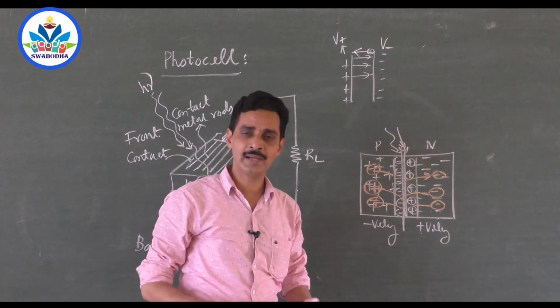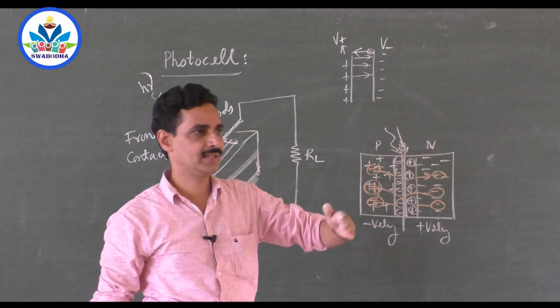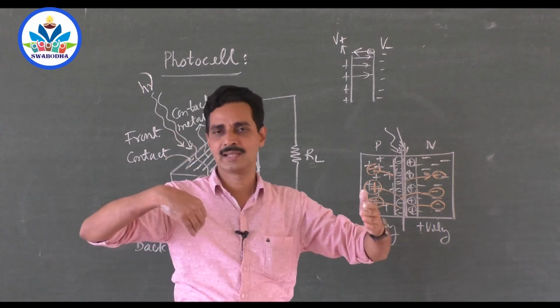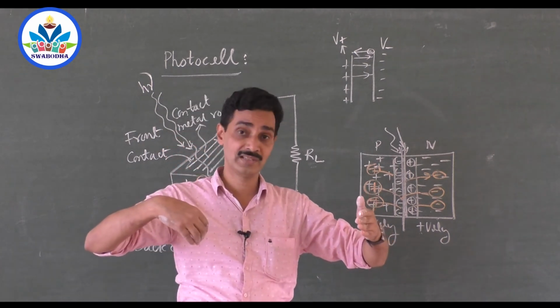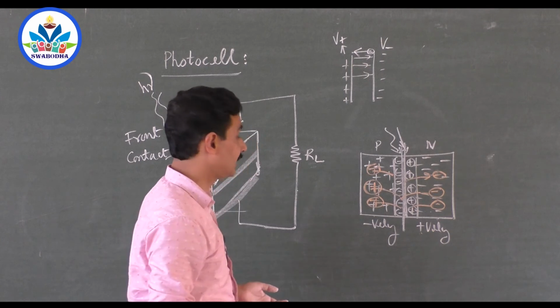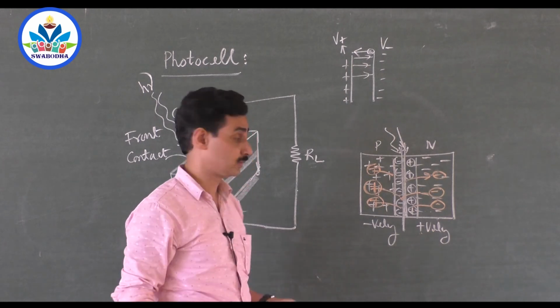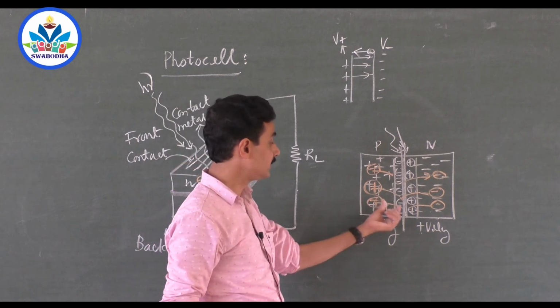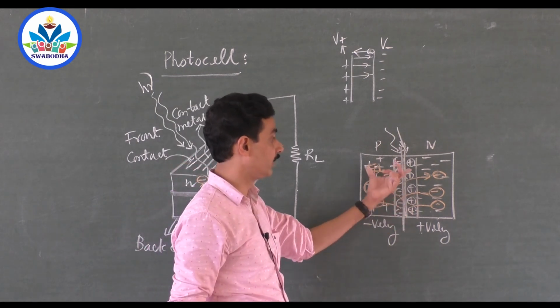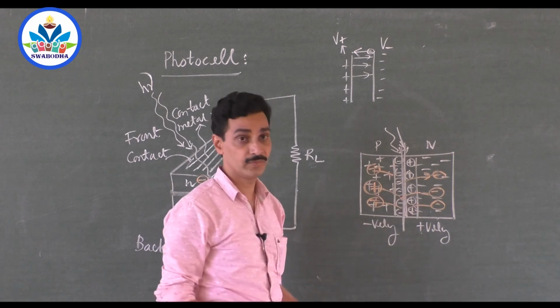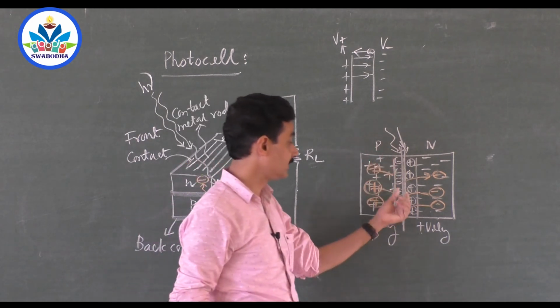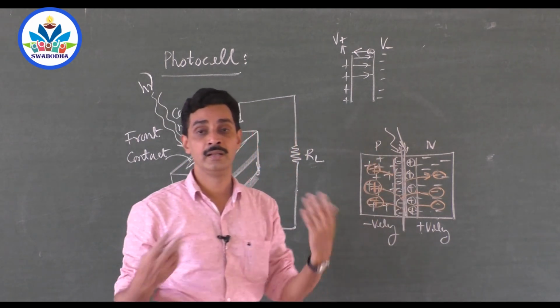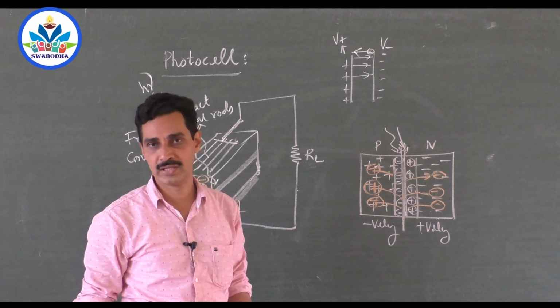Inside the battery also the same arrangement is done. One side is having higher potential, another side is having lower potential, electric potential I am talking, and that can make the charges move. So here, once these electron hole pairs move away after generation, we have three processes: generation, separation, and then acting as a cell, development of EMF.